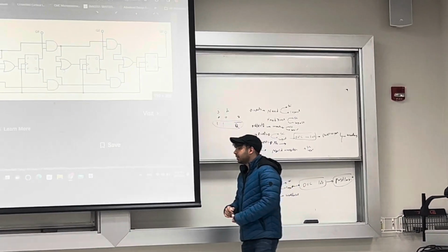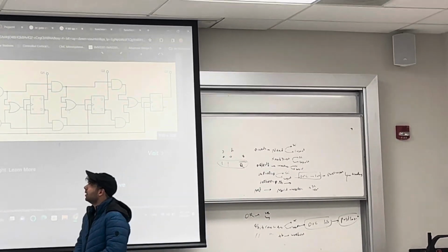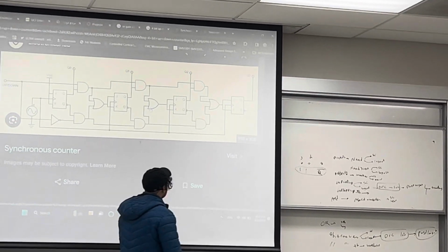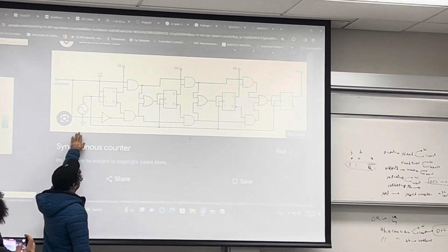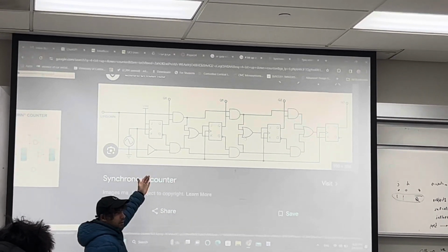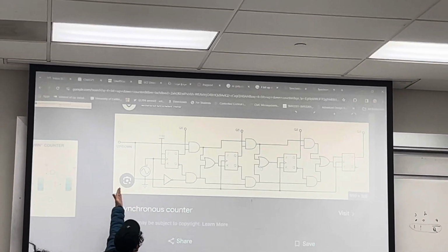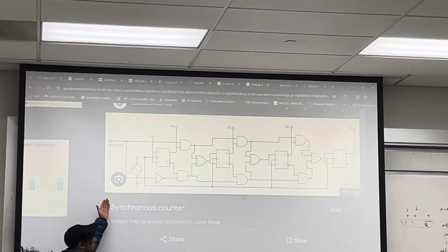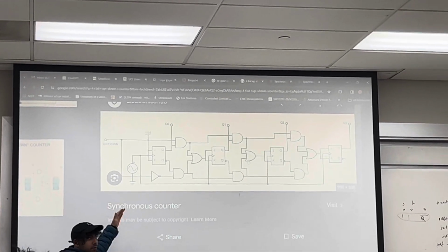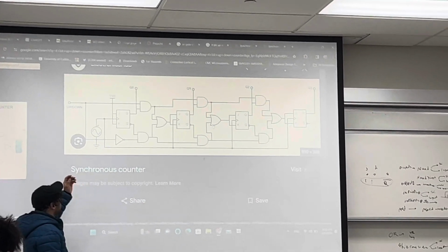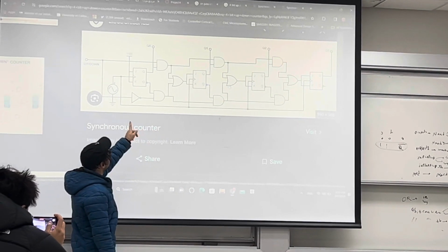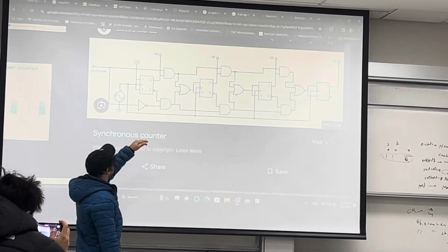So how can you test this circuit? Look, the clock will be V-pulse. So you have V-pulse again, same as the JK flip-flop. You have one VDD that's connected to the J and K, so that will be 2.5 volt. You have up and down. For the up and down, use the VDC. If you want to do the up counting, put 2.5 volt. If you want to do the down counting, put 0 volt. And then you have 4 outputs, Q0 to Q3, and show these outputs.